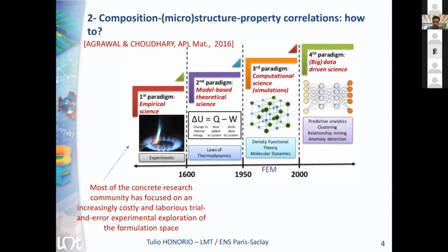The other three paradigms are related to model-based approaches. For the model-based approaches, you have micromechanics, which arises as a very good candidate to establish composition-microstructure-property correlations. More recently, not that recently, we can also use computers to do simulations and try, by means of numerical samples, to estimate and understand, and why not also optimize, the behavior in applications for cement-based materials.